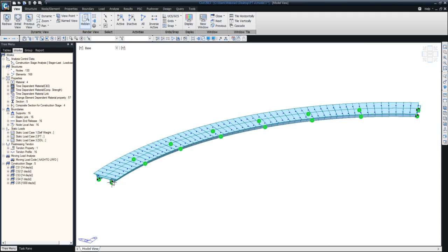So that member is very essential. If dummy elements or the transverse member is not in place, then there is no way that one girder line is sharing load with the other girder line, unless you make this as a finite element model with the webs and deck slab, everything with plate elements. And for concrete bridges, I would not recommend you to use plate elements for webs and all, because there's hardly any out of plane bending occurring in concrete thick girders or concrete webs. They are not like steel plate girders where that phenomena is quite important.